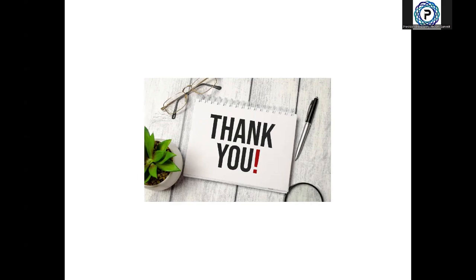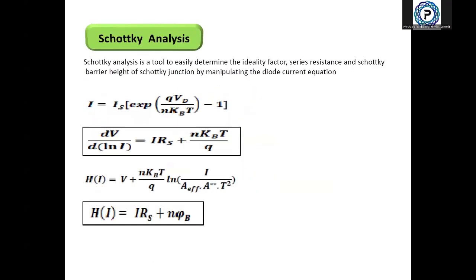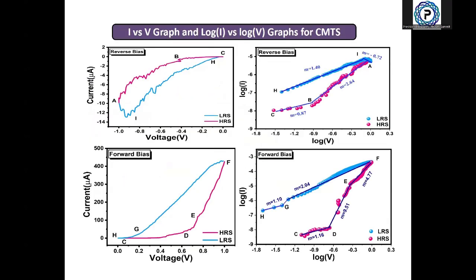Suman, can you go to your IV characteristics? You are talking about these three regimes, the ohmic regime, and then the slope, right? My question is, the voltage goes from -1.2 to -1.6, and then you see this steep slope, and then it goes to -0.3, and then again your slope changes as you are saying.